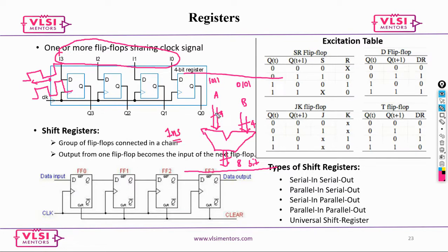So the moment you load your signal and it goes through your ALU, and it gets added and the whole process is done, it is going to be available at the flop. And this would be clocked again, at say another 4 or 8 flops called registers, and then they send it out. Now that means every 1 ns you keep getting a value.